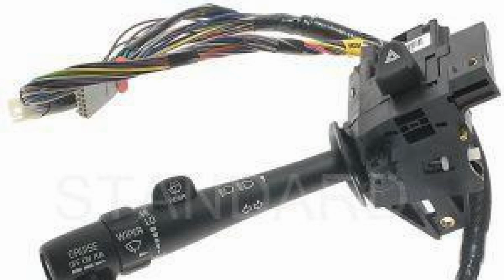If all hoses appear normal, the mechanic should perform a vacuum pressure test. He or she should also check the operation of the one-way valve, as well as the cruise control switch. The mechanic should also check blown fuses both before and after replacing components. A blown fuse may also indicate other electrical problems.